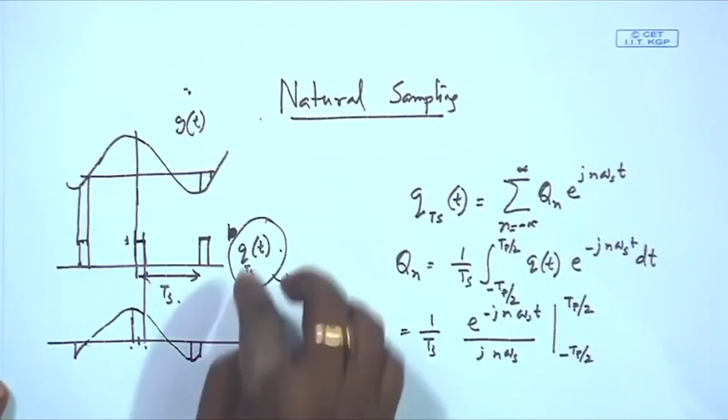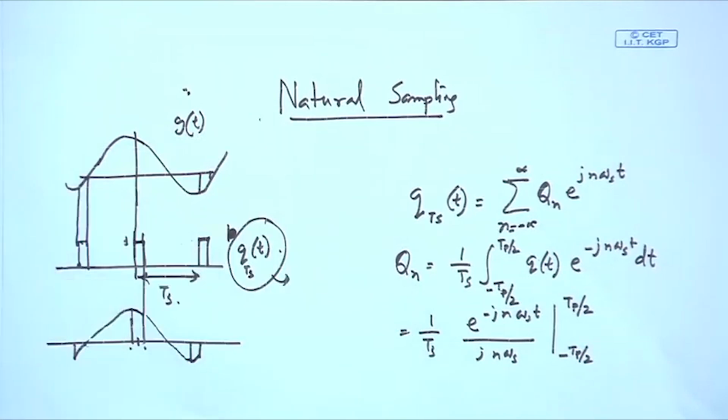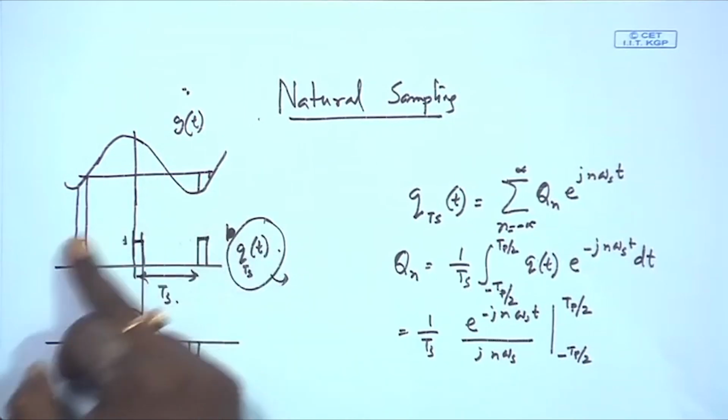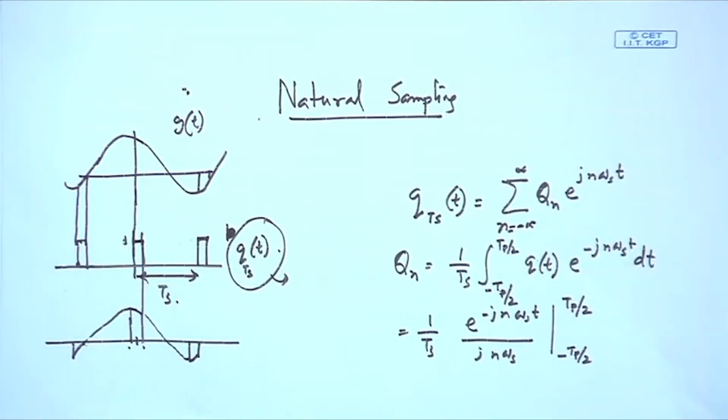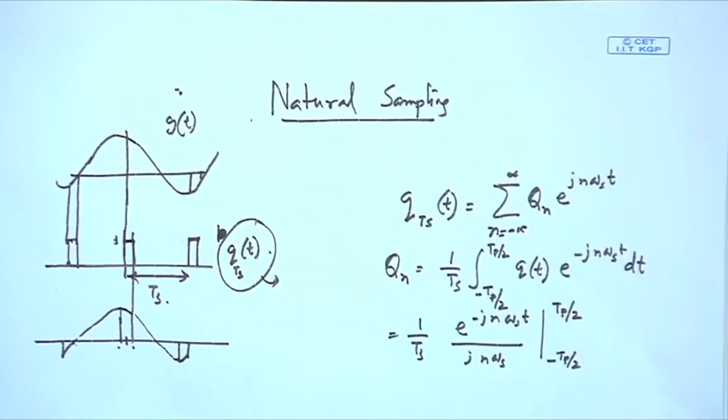What we are trying to do is, this sample q(t) is getting multiplied with g(t). We have already characterized the Fourier transform of this one, because we have got the Fourier series, and then you do a transform, you will get all kinds of delta functions with the corresponding strength q_n.